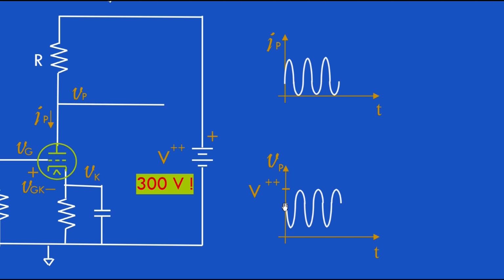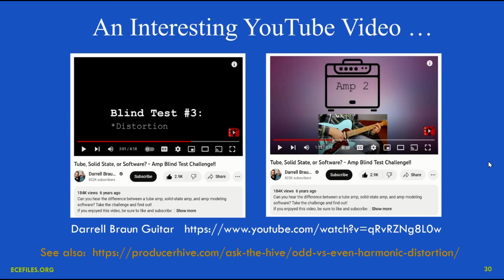At the output, the bottom half cycle of the sine wave is a little bit more spiky than the top half. And if we were to crank the gain up a little bit more, this would flatten out before this probably reached the bottom down here. Eventually it would flatten out as well, and you get different sounding distortion. And I would encourage you to listen to these tests and see for yourself what those sound like.